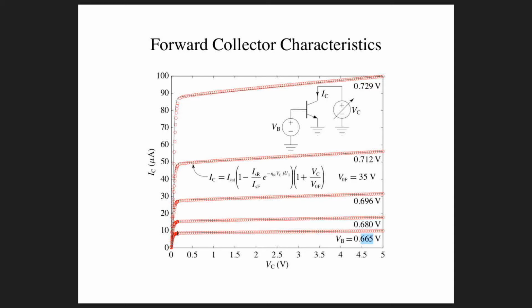And then when we get down to roughly 0.1 or 0.15 volts, that's when we start to see this thing really plummet and turn a corner and head towards zero, where the dependence is much steeper. So while this whole area is formally the saturation region, the forward active model actually describes the characteristics very well for several hundred more millivolts decrease in the collector voltage.